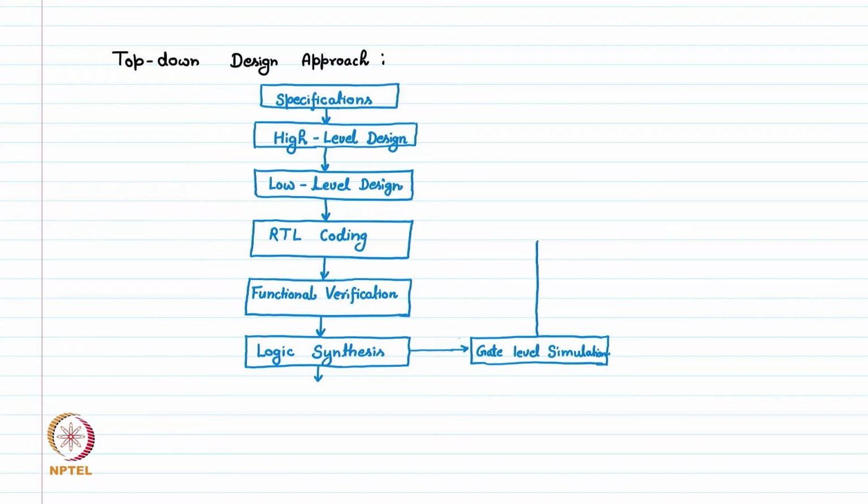And we go back to the RTL coding to make any change, or even this is sometimes connected to verification as well. We do verification as well when we do all these simulations, and once we are okay with the design whatever we have synthesized, then we go for the next step, which is place and route.